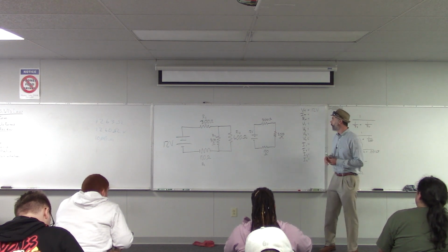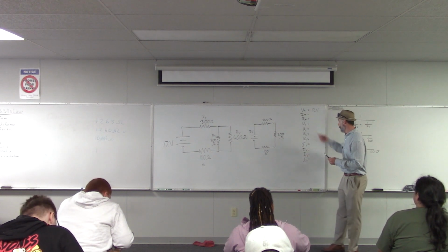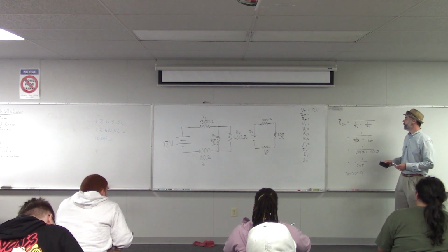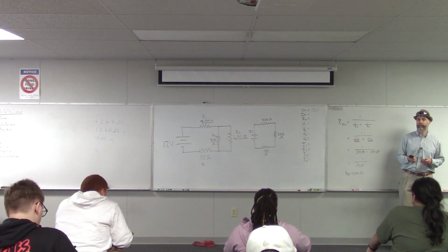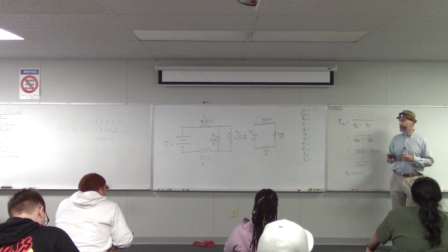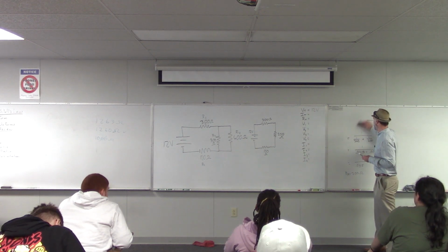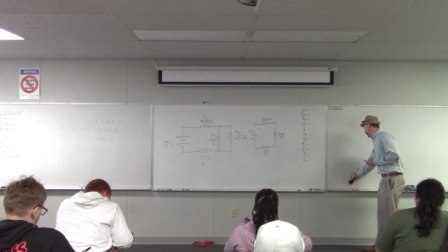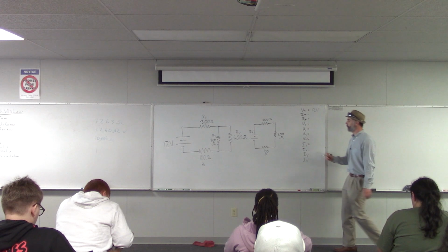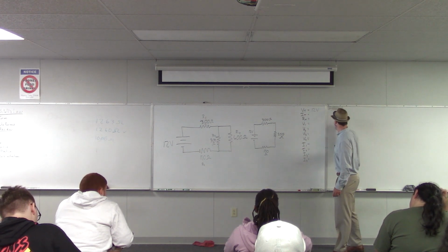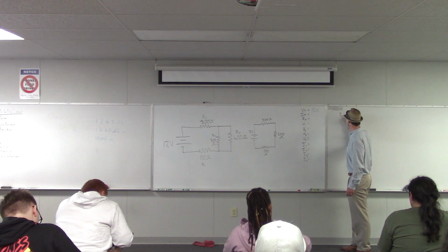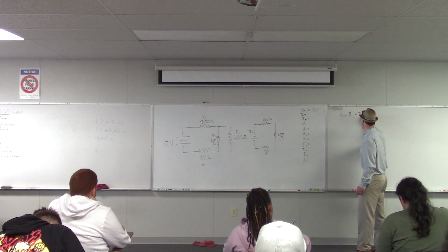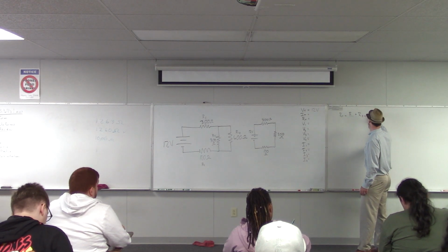Now we're still trying to get down and find that one equivalent resistance for the whole circuit. So what can we do now? Add them all up. Yeah, we can add them all up because they're all in series now, and that's the way that you find an equivalent resistance for a series circuit. So our total is R1 plus R34 plus R2.